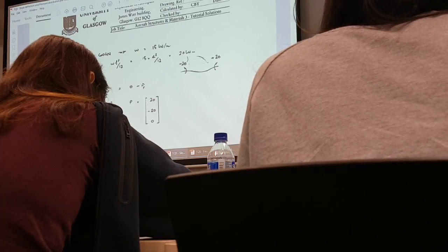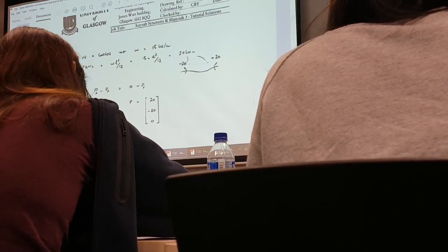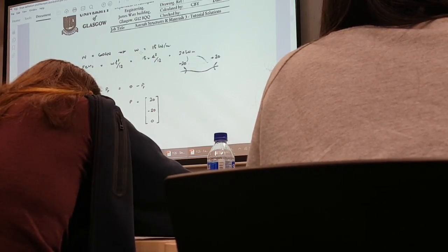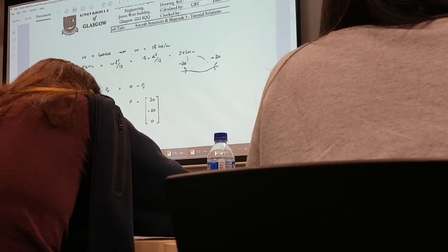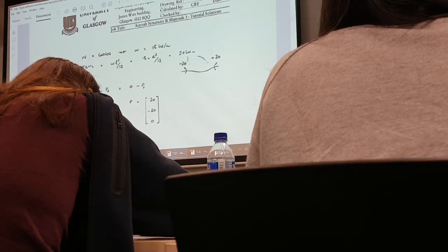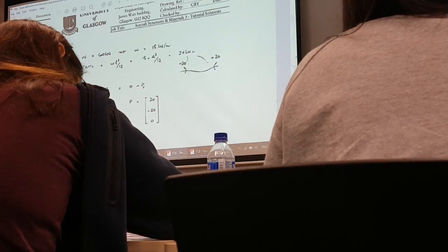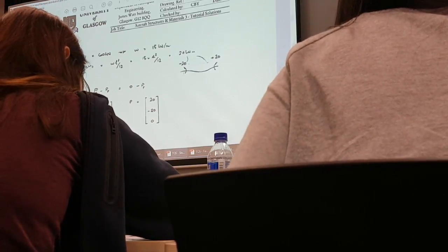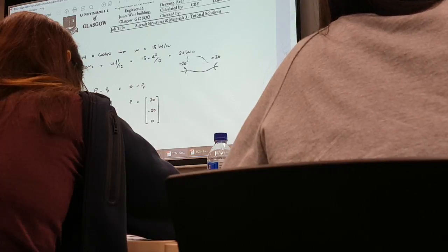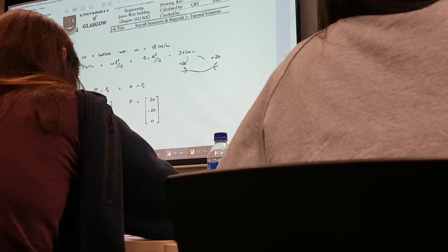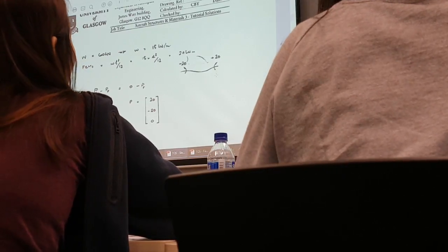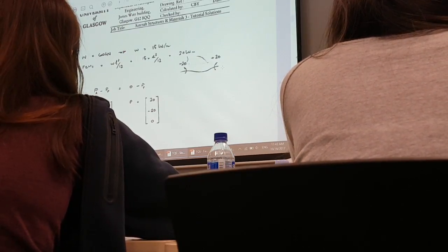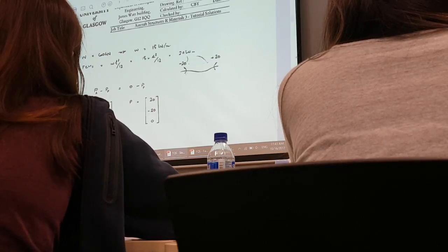Okay, so that everyone can see, right? You have obtained the small w. From there, you can use the FEM equation, which is small w L squared divided by 12. You will get the fixed end moment on the left-hand side as 20 kilonewton meter, in the counterclockwise direction, and the one on the right-hand side is 20 kilonewton meter in the clockwise direction. This is what forms your PF.